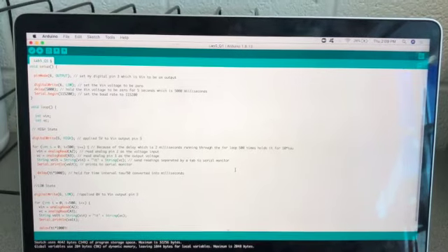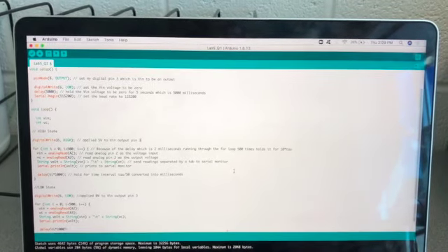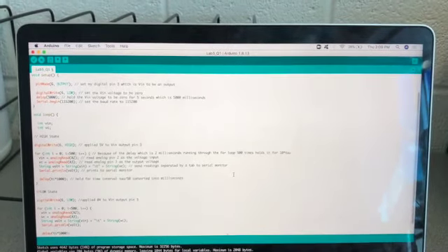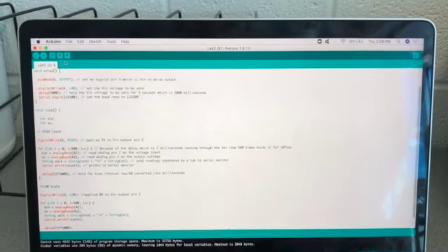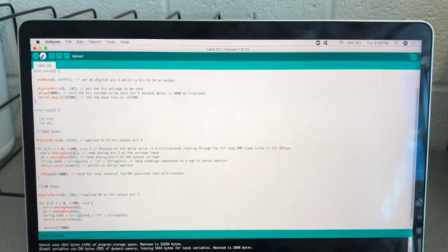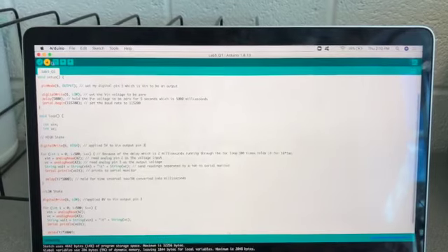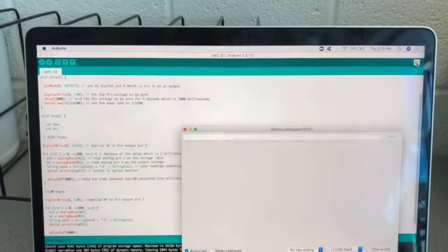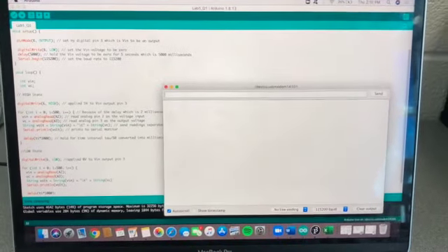Going through the loop, I read A2, which is Vin, and read A3, which is Vc. I communicated to the serial monitor to print the readings. Then I delay for 2 milliseconds, making our for loop iterate 500 times because 500 times 2 is 1,000 milliseconds. I then did another for loop applying 0 volts with all the same conditions.